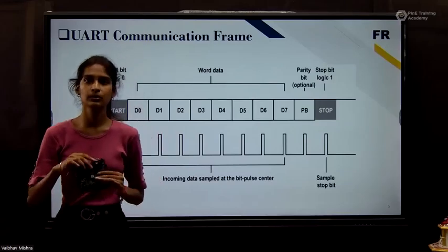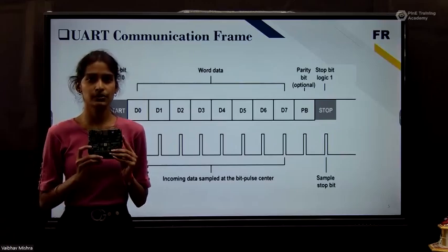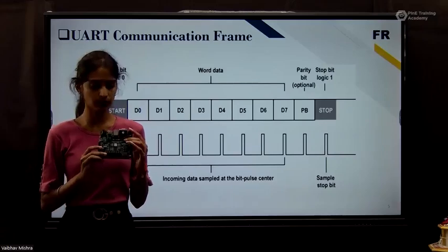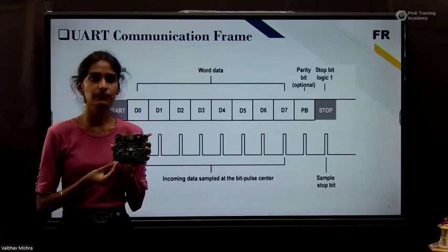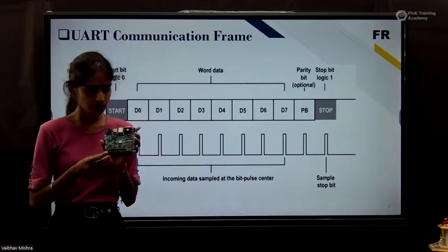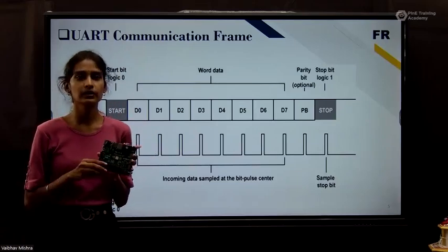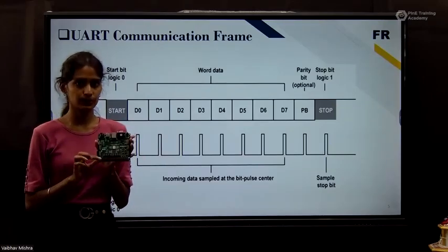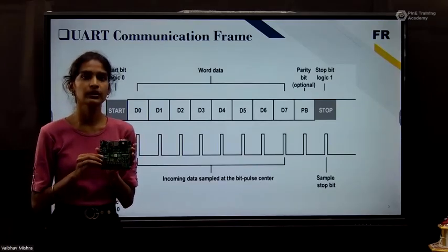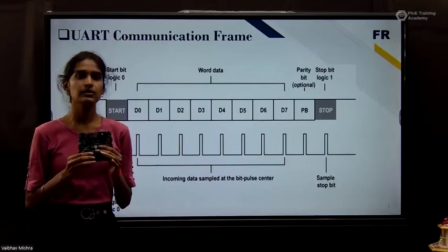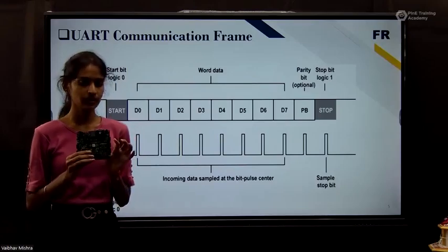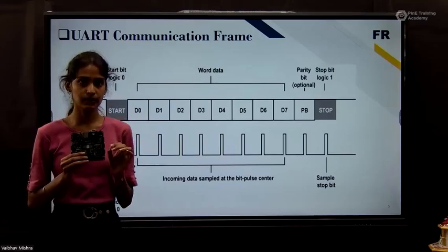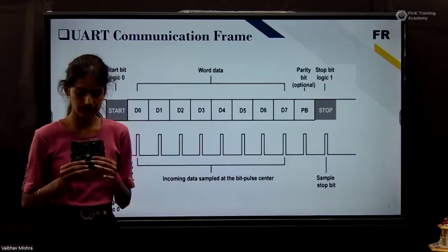Here we have an FPGA board, which is a Nexys A7 FPGA. Through this FPGA, we can easily visualize our UART transceiver project. There are a total of 16 input pins, which are switches. Through these switches, we can give the input, the data we need to transmit serially. After the FPGA is programmed, firstly we give input to it, and after giving the input, there is a need for serial communication. So there are a total of 5 PMOD ports. A PMOD port has multiple input-output pins, which are the serial communication pins, along with the VCC and ground pins.